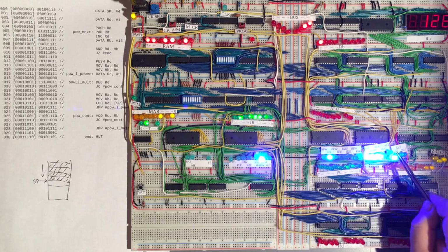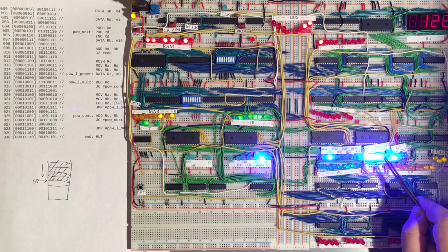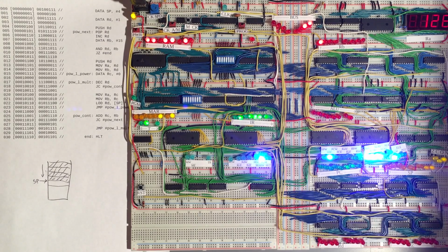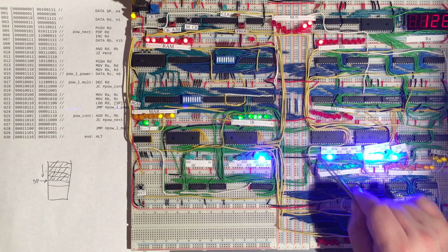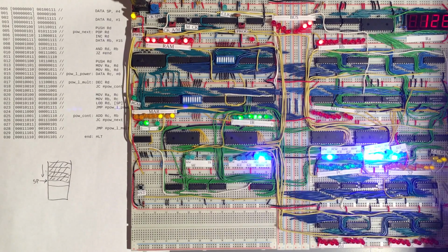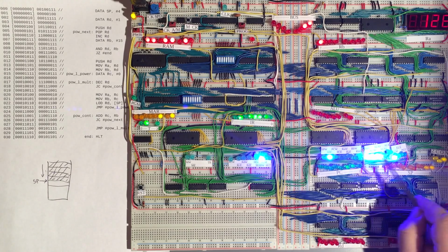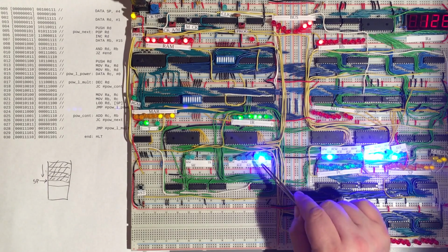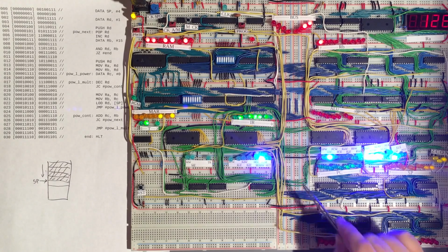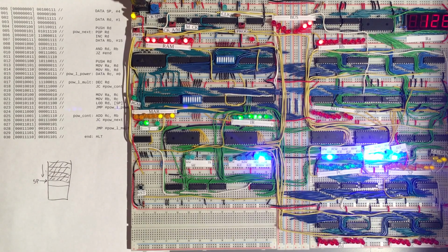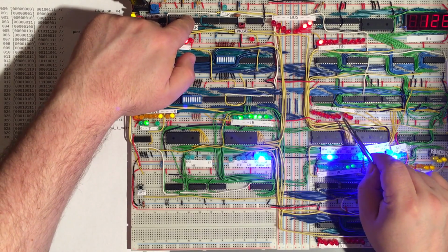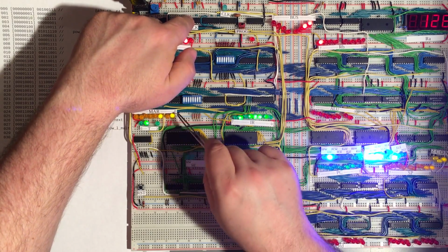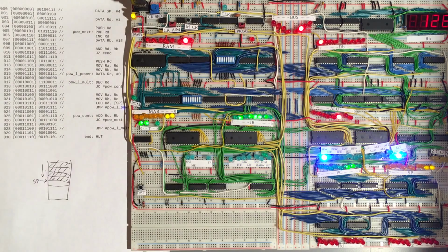And so these operations correspond exactly to what we would do if we simply did an increase. But of course this is not simply an increase, because at the same time as this calculation of the value of the stack pointer plus 1, we're also writing the current value of the stack pointer into the memory address register. So we can do all of that on time t2. So all right, let's do that. So this 3 will get 1 added to it, and we'll get a 4 here, but the original 3 will then appear in the memory address register.